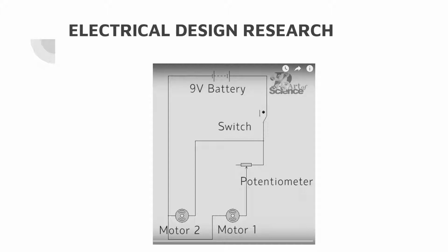As far as electricity goes, we weren't sure how much power we would actually need. After looking through a few forums, we decided upon a 5-volt power source in the form of a portable phone charger. The charger was able to push out a total of 2.4 amps, which worked in our favor as DC motor speed responds better to changes in amperage versus voltage.